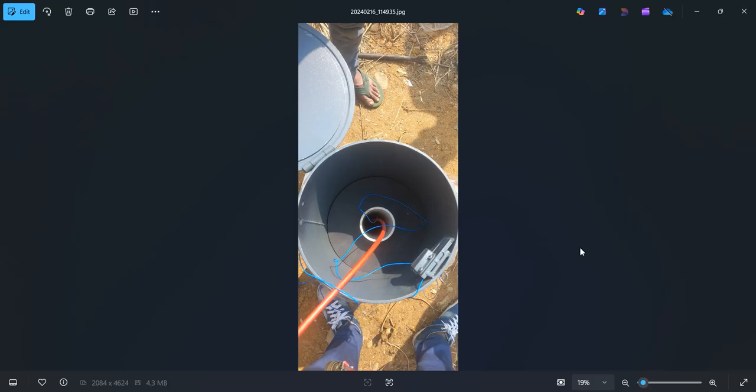And when we have a very long period seismic station, we should have a few considerations, in which the lightning or over voltage protection should be taken care of. And then when you have more noise, we need to make sure that this is installed even deeper, because sometimes when the sensor is installed 1 meter below the ground, you may or may not have the disturbance, and if you have disturbance you need to go deeper. So the ideal installation depth would be approximately 5 meters.